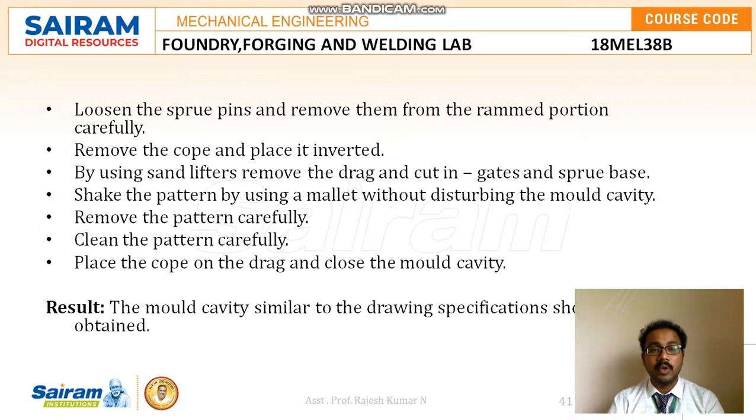So remove the cope and place it inverted. By using sand lifters, remove the drag and cut the gates and screw base. Shake the pattern by using a mallet without disturbing the mold cavity. Finally, remove the pattern carefully and clean the cavity carefully.